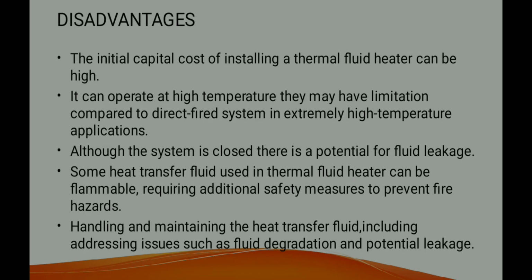Let us discuss a few disadvantages of a thermic fluid heater. The initial capital cost of installing a thermal fluid heater can be high. For installation and service, the cost will be high. It can operate at a high temperature, but it may have a limitation compared to a direct fire system in extremely high temperature applications. As we compare with the direct fire system, it is an indirect fire system, so the temperature application will be less compared to the direct fire system.